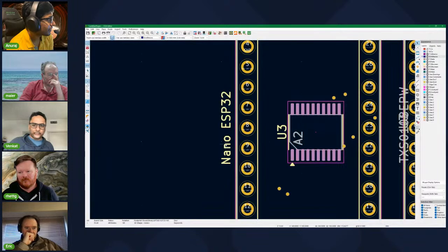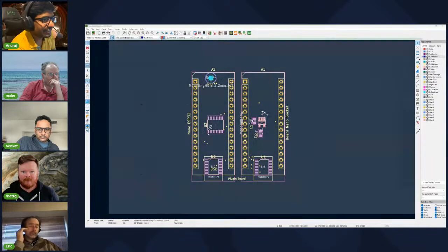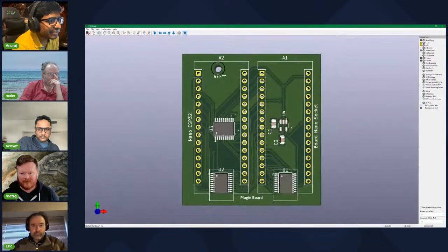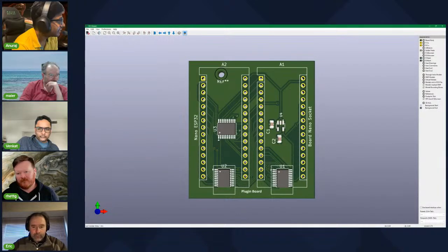Okay. Yeah, I'll have to see photos to really get it, I think. This is a 3D simulator or renderer. So after you solder here, you will solder the male pin headers here, and on the left side you will solder the female headers, and then on the left side you can plug in the nano ESP32. After this, these male sockets can go into the tumbler port, which already has the female. Okay.